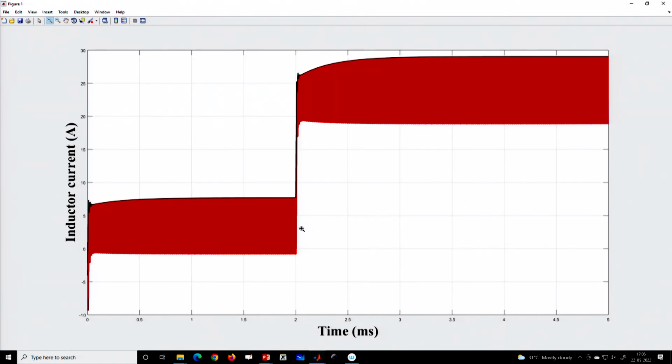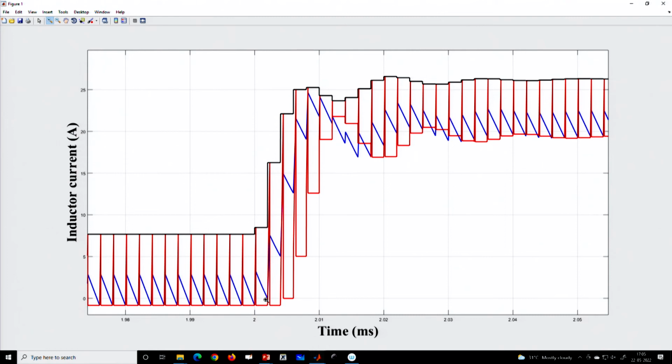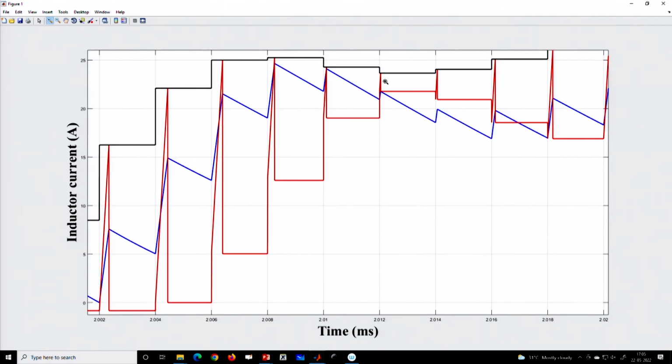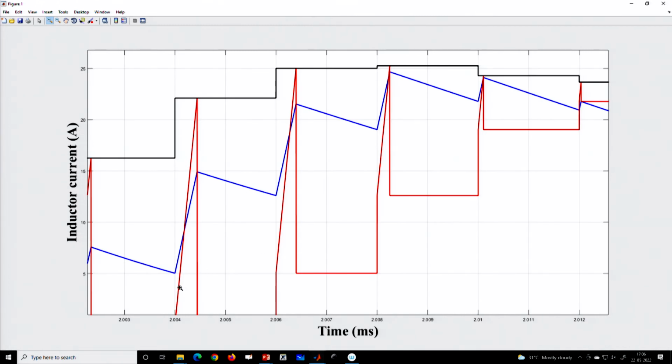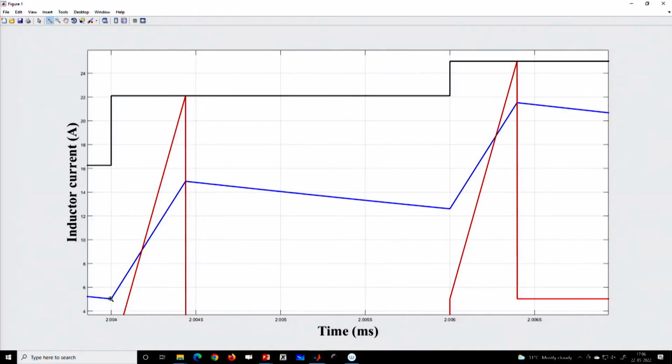If you take a transient case, I just want to emphasize, let us first consider maybe here. You can see this point, this is the inductor current for this cycle. For this cycle, the valley point of the inductor current is here. So, you can interpolate, and this is the valley point. That means your ramp is added; if I further zoom into this cycle, this point is interpolated here and then we have added this slope.